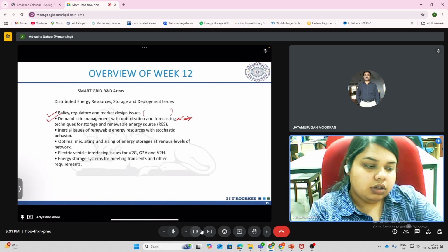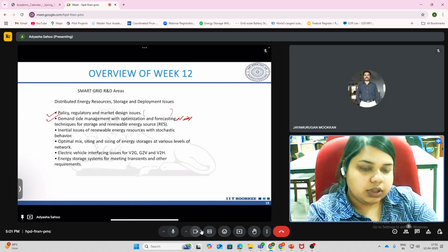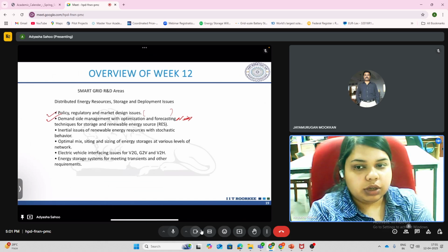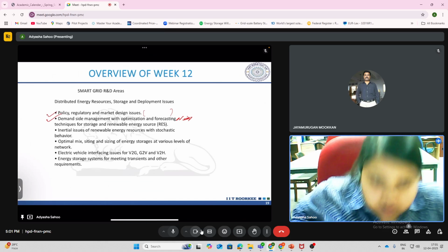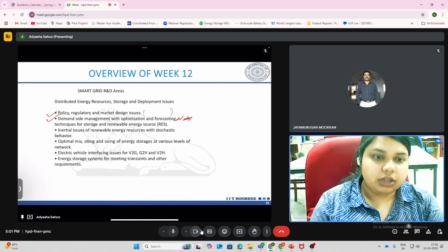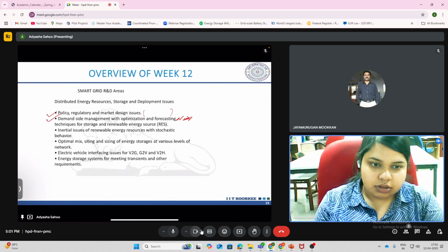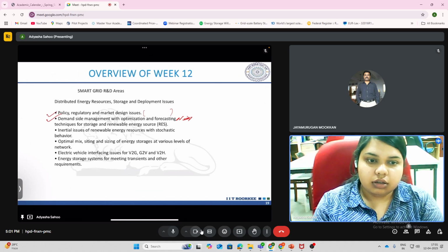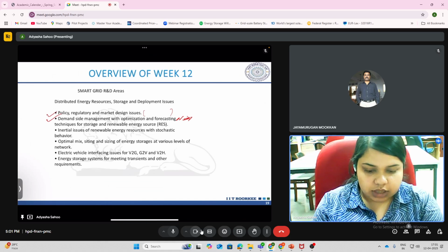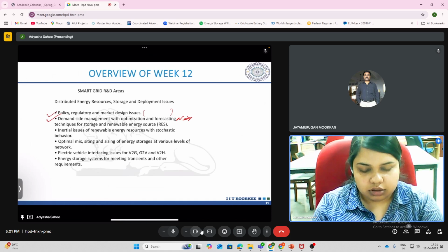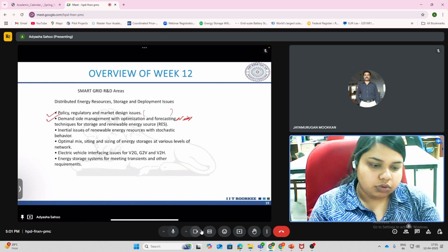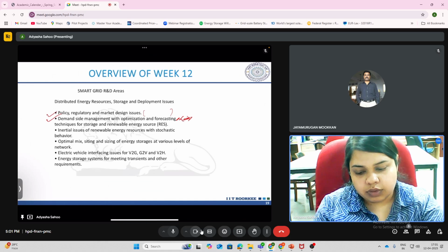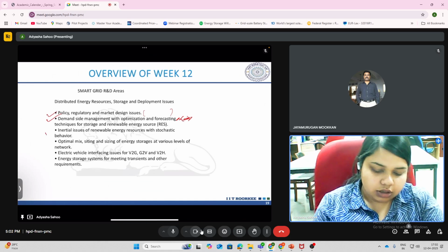So earlier we used to use DC power flows because we were mostly focusing on transmission system studies where the voltage issues were not so prominent, because the effect of reactive power and the active power can be decoupled very easily in the transmission system. But coming to the distribution system, the active and reactive power cannot be decoupled in the same way, and hence these require considering them simultaneously and developing the algorithms in the way that both the active and reactive power are being considered.